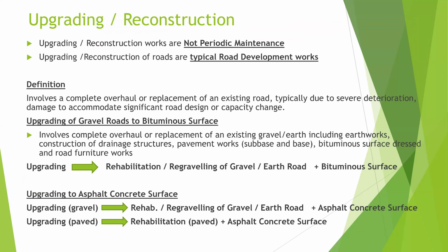And by definition, we are saying that, yes, it involves a complete overhaul or replacement of an existing road, typically due to severe damage to accommodate significant road changes. Now, you can have upgrading of gravel roads to bituminous surface, which involves all the rehabilitation, the regraveling of the gravel and the earth road, and then finally you seal it with bituminous. That is for changing it from gravel to bituminous surface.